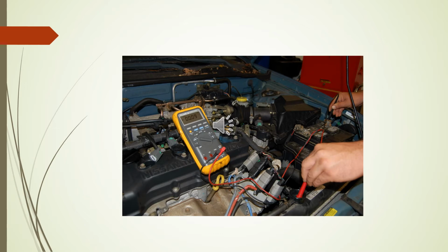The diagram shows the way of measuring galvanic corrosion or electrolysis corrosion. The first step is to set the digital multimeter to DC volts, and place the red probe, which is the positive, right inside the coolant, and the black probe is placed on a good ground. This could be a sheet metal, or it could be an engine block, or it could be the battery. In this case, it is the battery. And take the voltage reading.